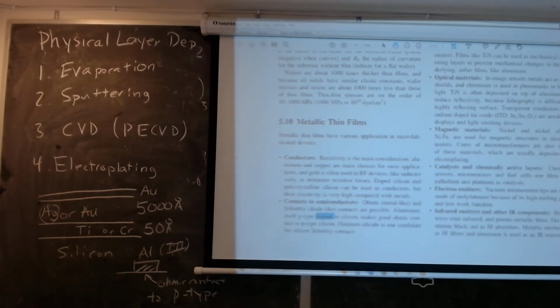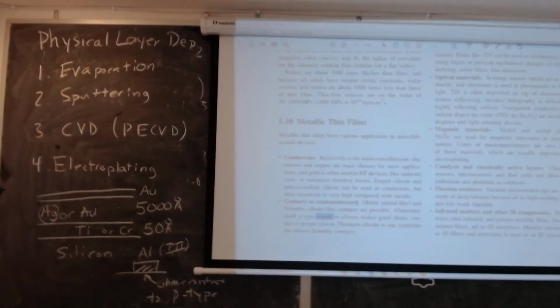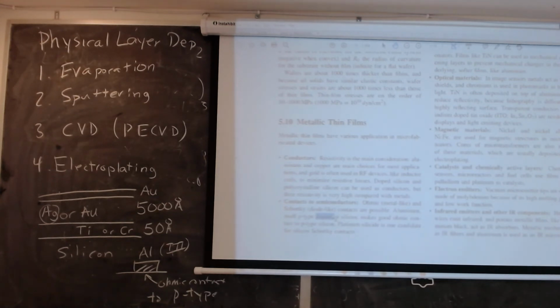So anyway, I want you to just generally be aware of the fact. I don't want you to try to memorize all the different types of ohmic contact material, but what I want you to understand in general is if you're making a contact to a semiconductor, it's very useful to use a metal that contains dopant atoms for the particular type, N or P.